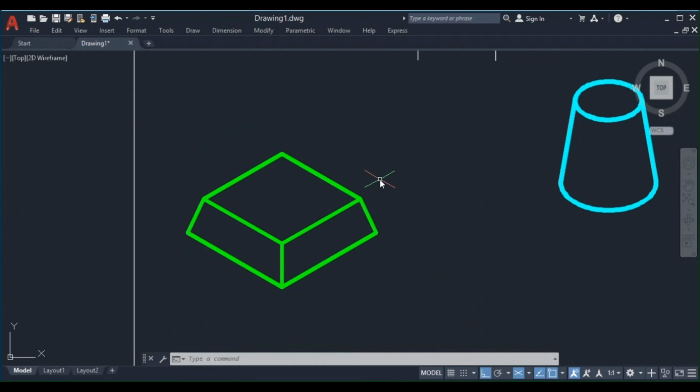I repeat the problem. Draw the isometric view of a frustum of a hexagonal pyramid. The sides of the top and bottom faces are 15 mm and 30 mm respectively, and the height is 50 mm. Bit number 1: the frustum is going to stand with its base on HP.